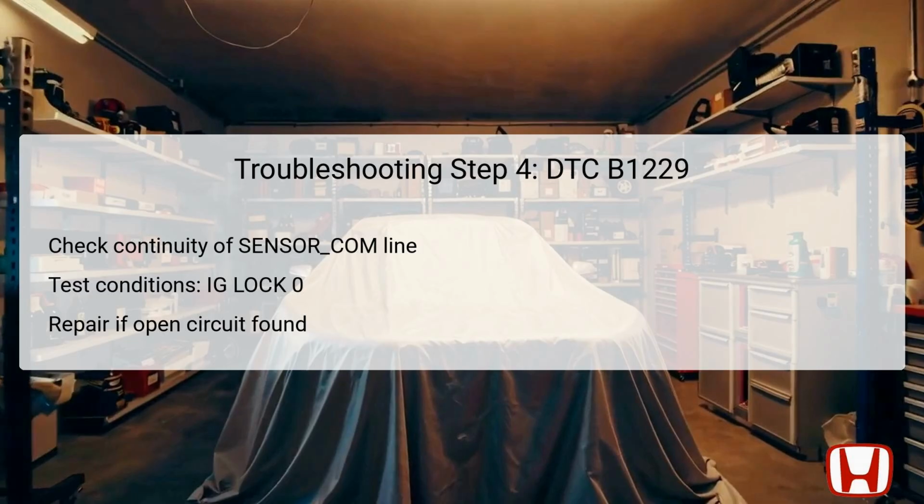The final troubleshooting step focuses on checking the continuity of the sensor COM line, another vital element in the sunlight sensor circuit. Similar to the previous step, ensure the ignition is in the lock position and that both connectors, climate control unit and sunlight sensor, remain disconnected.